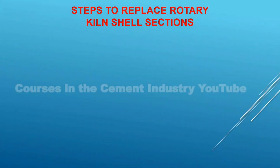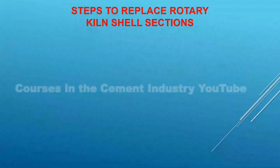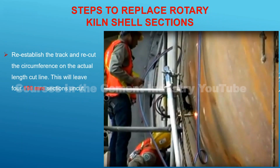Step 8. The first cut must be 150 mm within the required length around the circumference, leaving 4 sections intact, approximately 300 mm wide at 12, 3, 6, and 9 on a clock face. Step 9. Re-establish the track, and recut the circumference on the actual length cut line. This will leave 4 150 mm sections uncut.